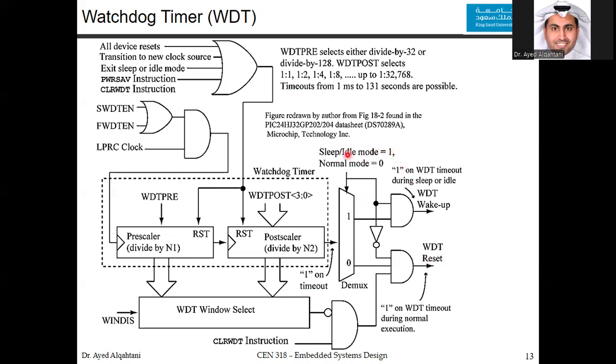If not, meaning that you are in the sleep or the idle mode, then the watchdog timer here will wake up the processor. By the outputs here, it means that this will cause the reset. The value will cause a reset. It will be connected somewhere that it will cause the reset behavior. And this one will be connected somehow to do a wake up, generating the oscillator or making the oscillator run in the normal mode.